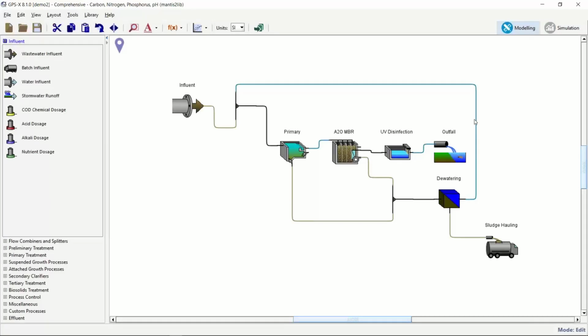And we got into this long discussion about the way that this person had set it up. And he was a little bit confused about why he wasn't really seeing great MBR, A2O type BioP removal. The orthophosphorus was being removed, but not as low as he had expected. And then anytime he tried to optimize some other part, like to maybe change up the denitrification a little bit, it seemed to make the BioP worse. So what we did was we played around with his model, and I always remember this was when I was a bit more at the beginning of my career than where I'm at now.